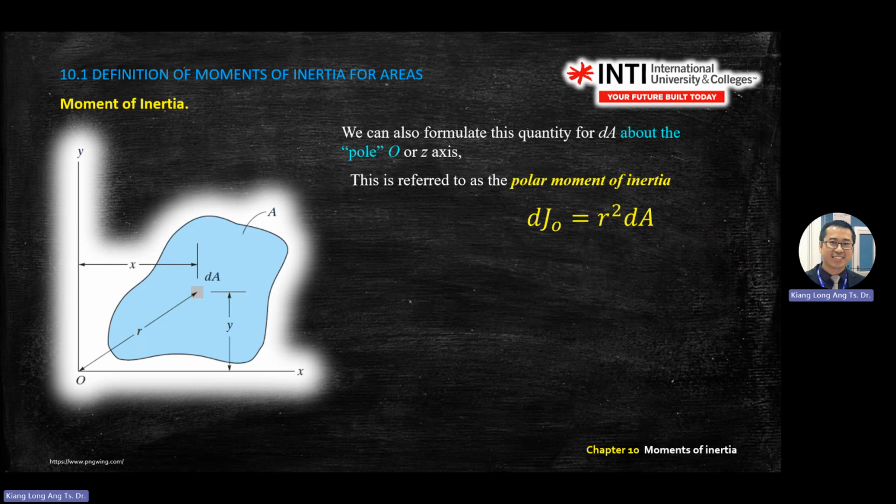Okay. Now, the formula will be almost the same. The left-hand side will be the inertia component. Just now, it used I. But now, because the question mentioned polar, you change the I to J. And on the right-hand side, just now for moment of inertia you used x or y squared, but now you use r.